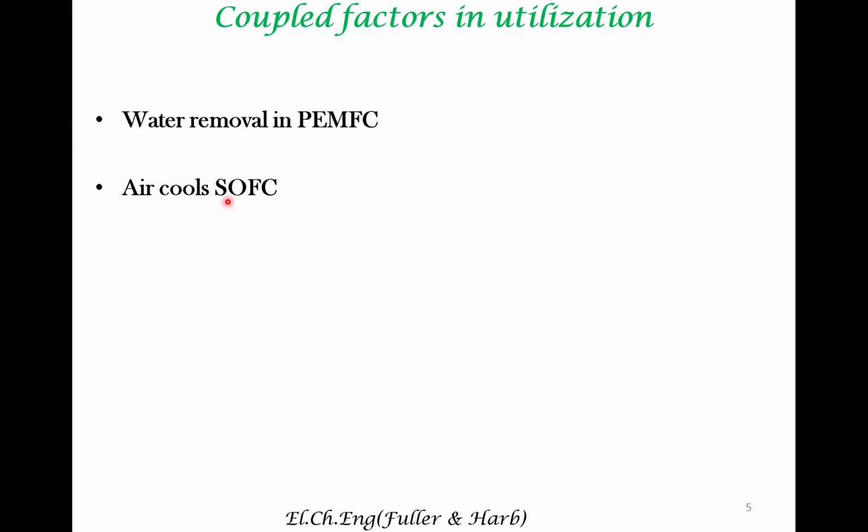So heat removal is very critical in SOFC, because if a lot of heat is generated and not removed, it leads to material degradation and fuel cell degradation. So one of the roles of air in an SOFC is to act as an agent for removing heat. If you supply too much air, you may cool down the SOFC. If you do not supply enough air, you may not be able to remove enough heat from an SOFC.